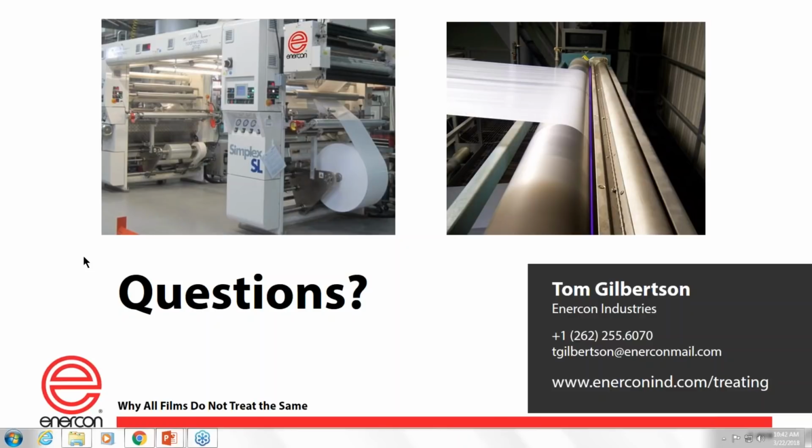All right, here's a question. Can you have a dyne level that is too high? Well, that kind of goes to over treatment. You can have dyne numbers that are high, not because of the number, but because of the energy that got put into the film to get that number, that causes undesirable effects. So for example, let's say you take a polyethylene film, you normally treat it to 40 dynes at a moderate 2 watt density. Somebody decides that they want to triple the watt density, and when they do that, now the material starts acting funny.